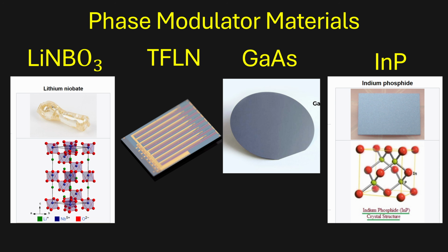An emerging technology is thin film lithium niobate. The more compact form factor allows for higher electric field strength and refractive index change at the same voltage. This results in a smaller device, better efficiency, and faster bandwidth, often well over 100 gigahertz. Gallium arsenide is less common for fiber, but it is an alternate choice for space laser links because of its thermal and radiation properties. Indium phosphide uses different electro-optic effects, and it is a more mature technology that also achieves extremely high baud rates and efficiency.